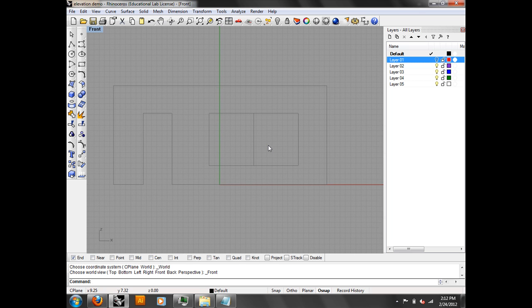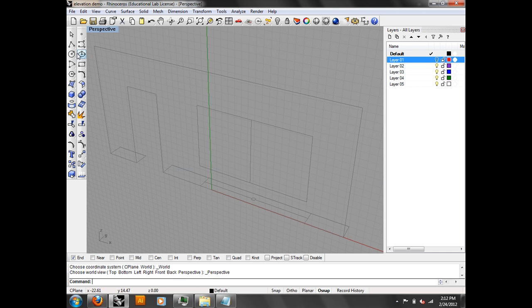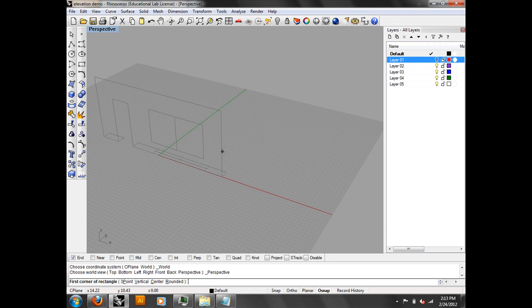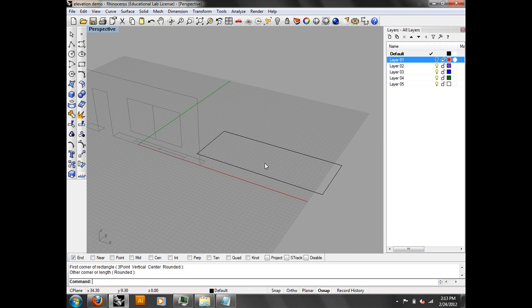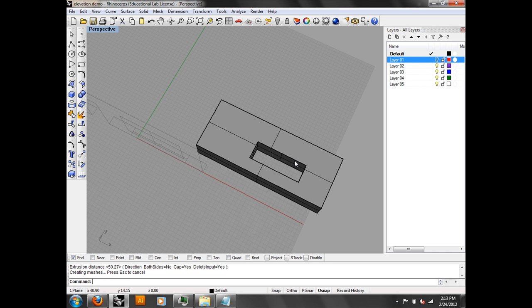One of the things I'm going to talk about today is that you've got these drawings from CAD. And one of the things I showed you a couple weeks ago that makes sense in Rhino is that when you extrude something, and a lot of modeling is extrusion, and it has another shape inside of it, and you cap it, then you get a hole in it. Now you could make the solid and then boolean the thing out and get the hole, but I find this to be a lot easier.